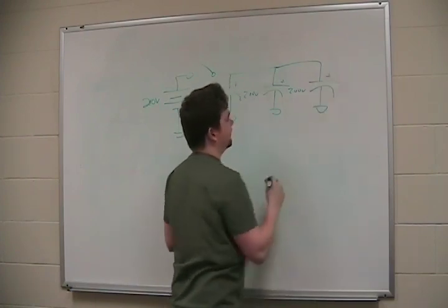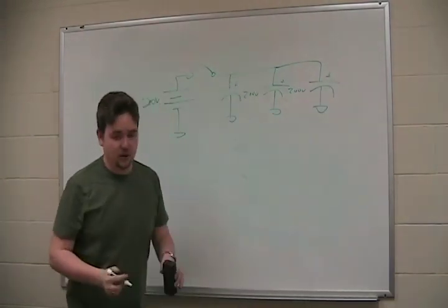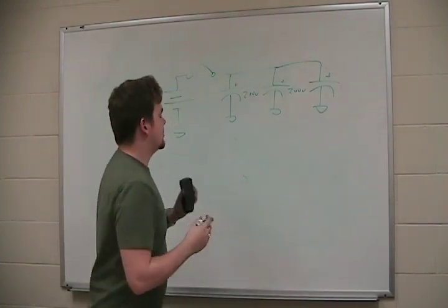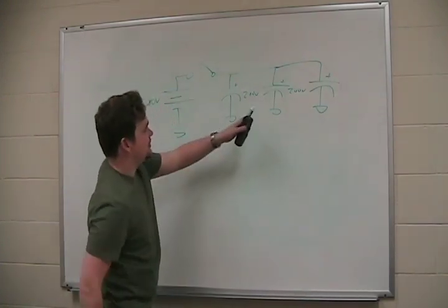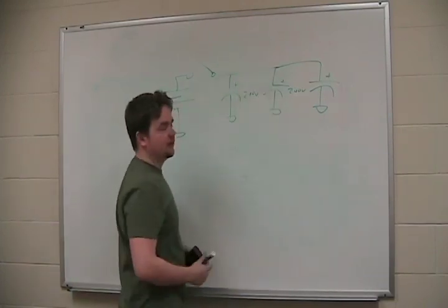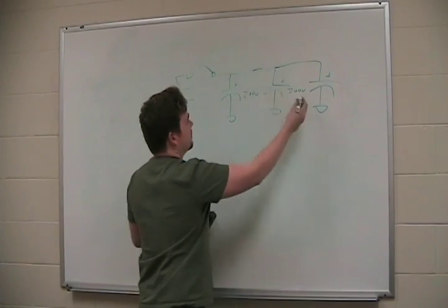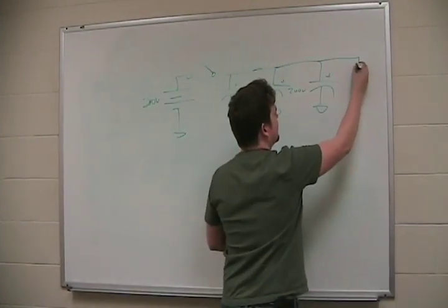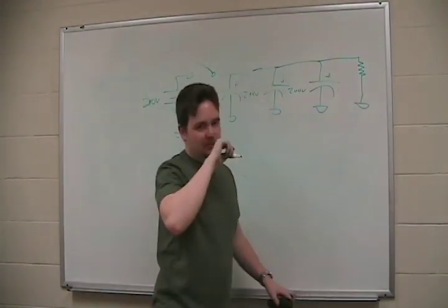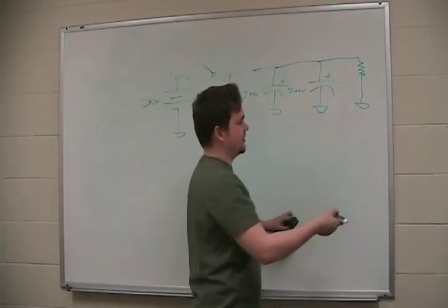3 times the current. Now, we haven't talked about power yet, but if you're charging 3 of these in parallel, that's 3 times the current of what it would be if we just cut this off. So we have to add what's called a bleeder in there. A bleeder is a very high resistance, very high.